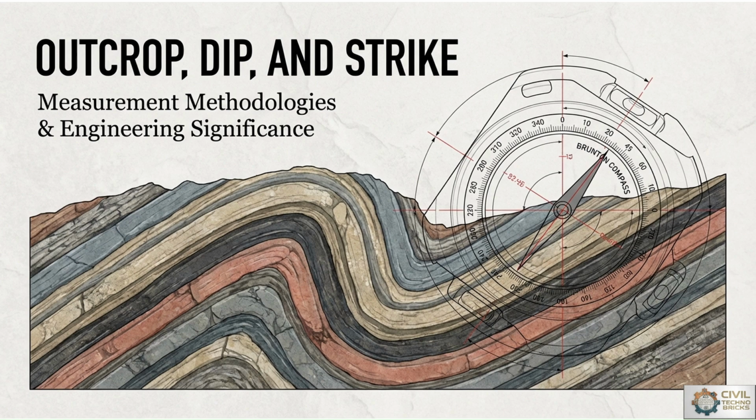Here, the most important concepts in structural geology are the outcrop, dip, and strike. These parameters help engineers to understand the orientation and behavior of rock masses beneath the ground surface. With reference to that structure, or we can say that the orientation, the civil engineer must decide their policy of the foundation before constructing any type of dam, tunnel, highway, or foundations for big massive structures. Engineers must know how rock layers are inclined and how geological discontinuities are oriented.